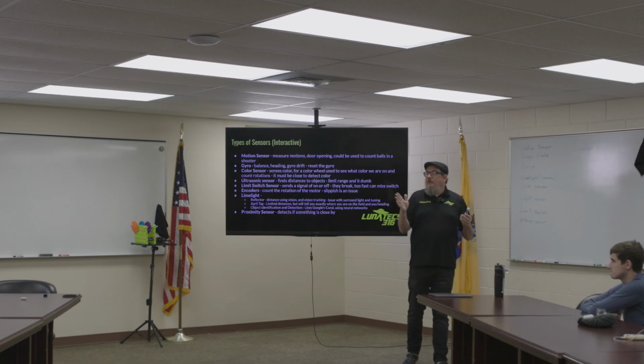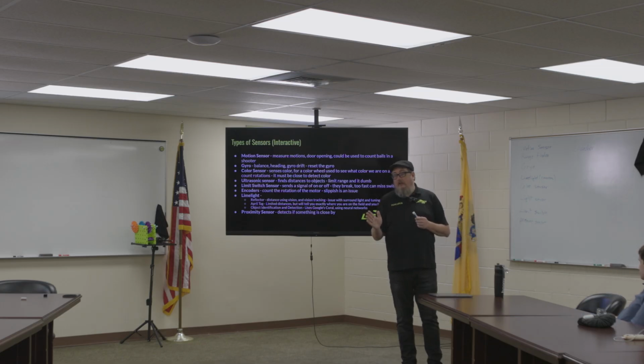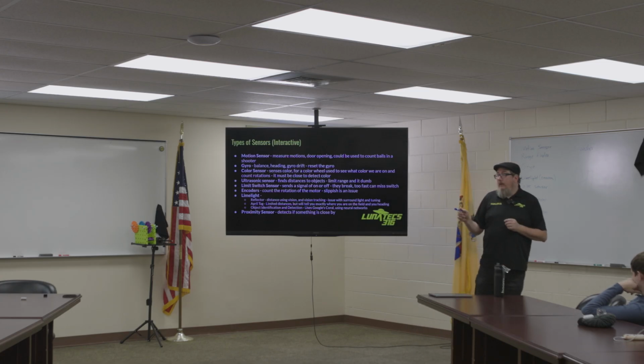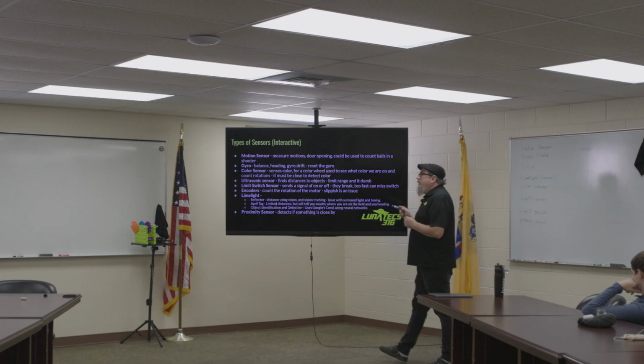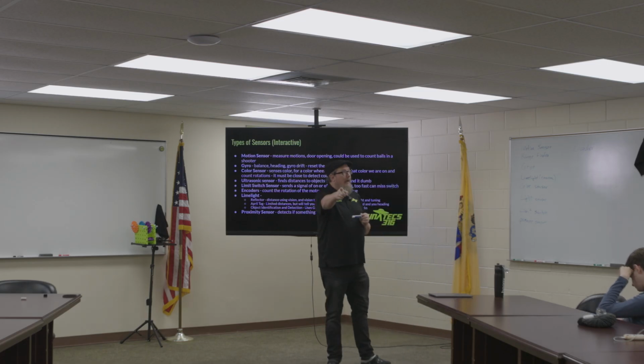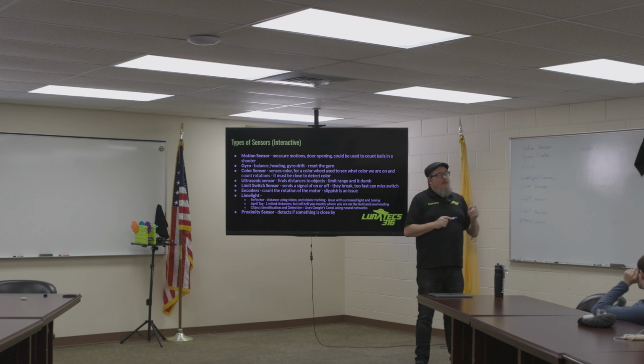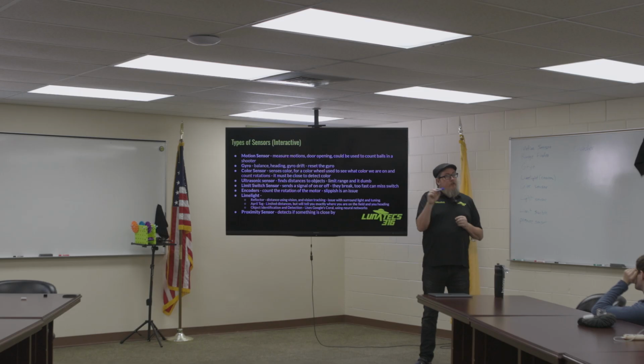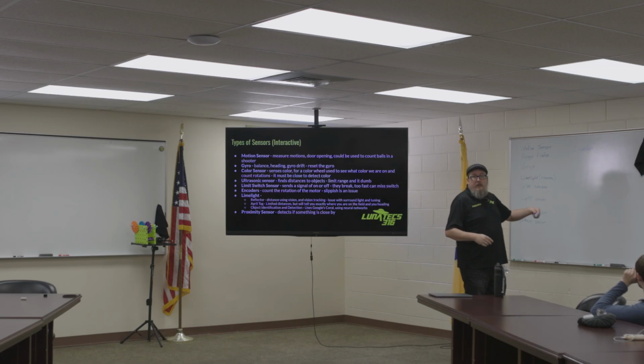And if I hook that up to gears, we just had the gear assembly, let's say it's a 4-to-1. How many times does the mechanism rotate on a 4-to-1 if I rotate the motor 8 times? 2. Correct. Did I get that right? Yeah, thank you. I am not mechanical. We will record the gears in our subsystems because when we are doing extensions of the elevator, we don't count encoder values, we count height.